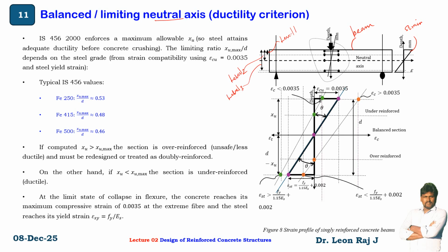At various points the strain is measured using a demountable mechanical strain gauge. Between these two points, you know the deformation. So this is the strain at level 0, strain at level 1, strain at level 2, and strain at level 3.